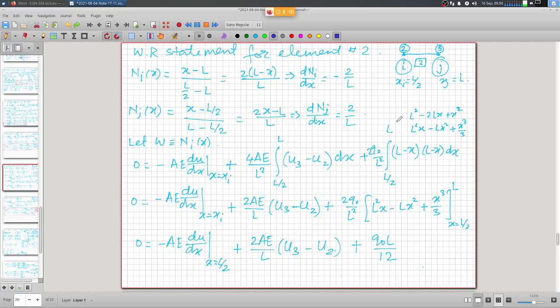forcing function changes, in this case I intentionally chose this linearly varying skin friction, then this term needs to be evaluated. So this term will have to be evaluated, and that is integrated depending on different element and different variation of skin friction or forcing function term, and you get what we call nodal equivalent values of the forces, equivalent nodal values of force. So distributed force is transformed into equivalent nodal values, and the idea is the distribution is such that the work done by the nodal equivalent values of forces in moving through these nodal values of the displacements that we have at the nodes is the same as the work done by the distributed force in moving through continuous displacement field. Right? So that is work equivalence.